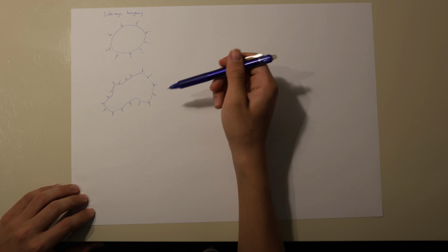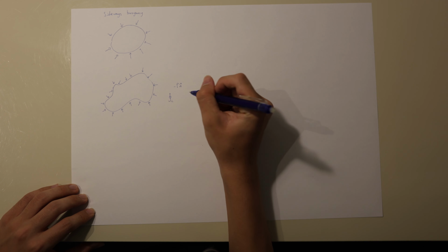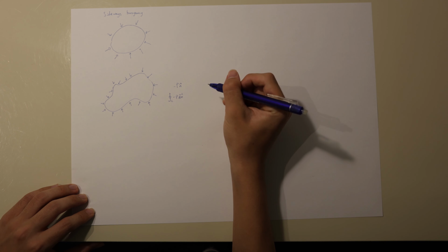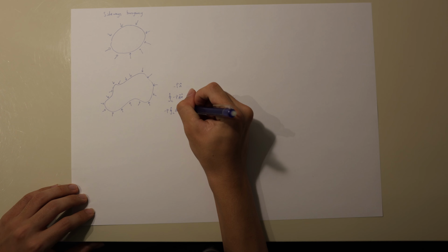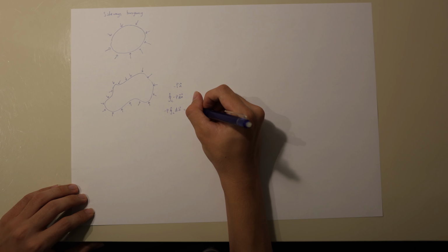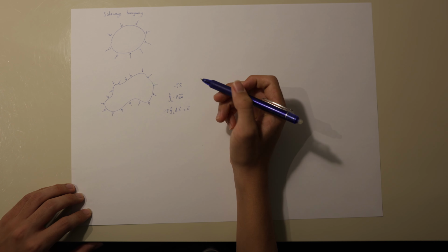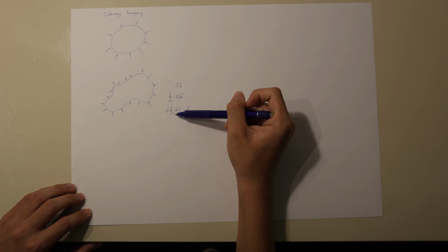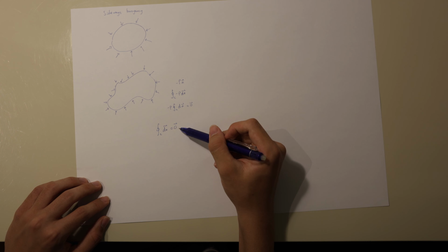That means the sum of all the different forces, when you integrate them together, will be equal to the closed loop integral around C of negative P times a small normal vector. Negative P is a constant, so you can bring it outside the integral, and what you're left with is this. And our goal now is to show that this integral here is equal to the zero vector. It doesn't equal the number zero, it equals the zero vector. And showing that would prove that no matter what shape it is, no matter what specific C we have, the sideways forces are always equal to the zero vector.